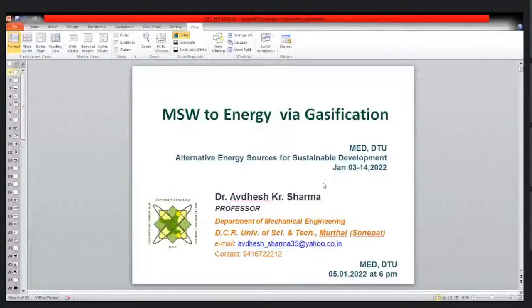The municipal solid waste, after converting into RDF, can also be processed through different gasification systems which use powdery form, for instance entrained gasifier, bubbling gasifier. So there is scope of using it without making any briquettes. When we have to use briquettes, we are talking about a solid biomass gasifier system. So we can see it that way.